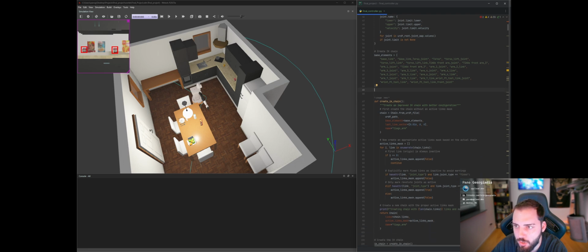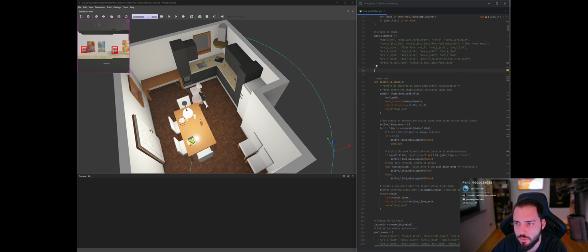A very critical aspect of the implementation is the advanced inverse kinematic system. It enables precise positioning of the robot's arm, like I said, based on the end effector for object manipulation. Inverse kinematics solves the problem of, given a desired end effector position in a 3D space, what joint angles are required to achieve this position.